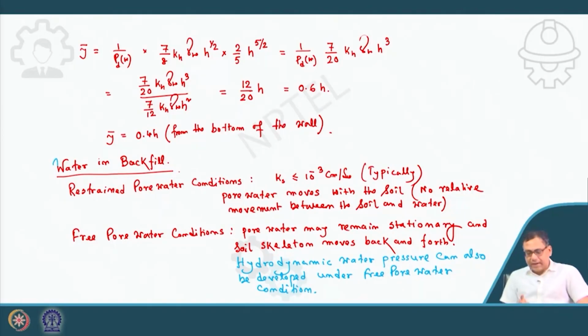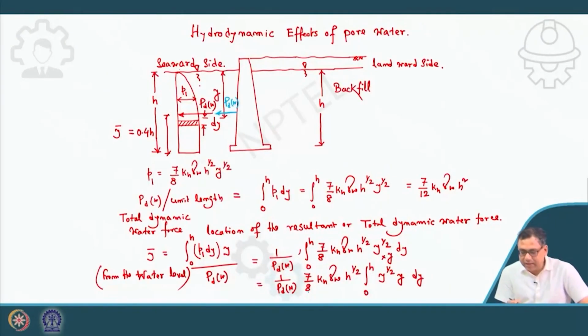So, remember that if it is free water condition, as I mentioned, when the permeability of the soil is very high, then the hydrodynamic water pressure or force can also be developed, and we have to consider this hydrodynamic force in the backfill side along with other forces. Clear? So, in free pore water pressure condition, both in the seaward side and the landward side, the hydrodynamic force will act. Clear? So, this is for the free pore water pressure condition.